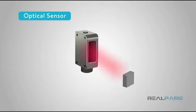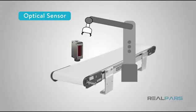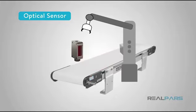Optical sensors have a much longer range than proximity sensors, but they are susceptible to dirt and other environmental and mechanical issues because they use light for sensing. We often use them where we are not picky about exactly where the target is, but we need to know it is there, like boxes on a conveyor, where we don't care where on the conveyor it is, just that it's passing by.